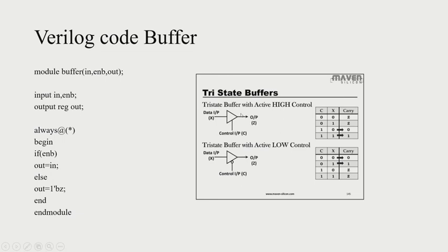Same thing, we are going to talk about the definition of tri-state buffers. Whenever the control input is high, then output will be equal to input. But whenever the control input is low or zero, the output will be in high impedance state. Same thing I have written in Verilog.